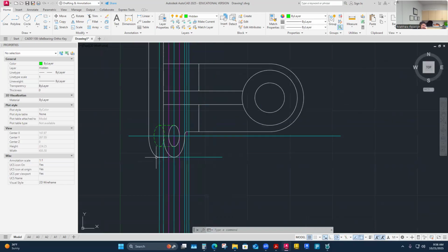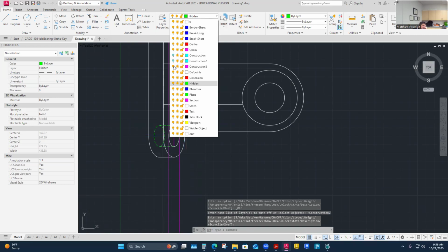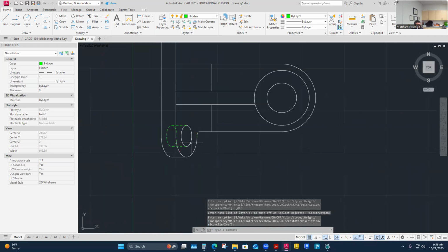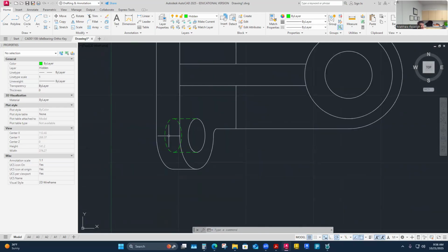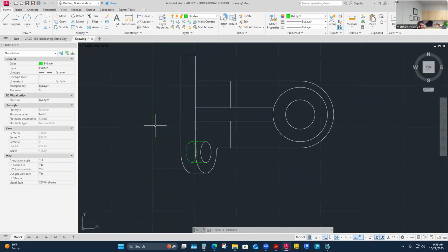So I'm going to copy all that stuff up and over to the other side or mirror it across. So I might just turn off these layers that I've used here and decide what stuff I'm going to copy. But that should be it, right? Yeah, I think so. I mean, I could put some center lines through there, but maybe I'll come back and do that last. And yeah, I think that's the correct profile that I would look. So let's make a mirror of that.